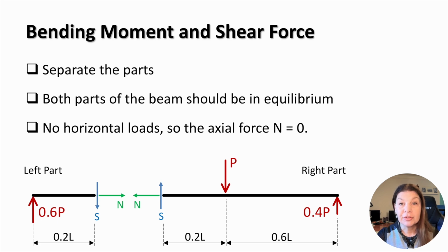As you can see, the force S is added in the opposite directions at the cut in both parts of the beam. This arrangement will cancel the force S if the beam is connected back. And the rotational equilibrium can be achieved through the addition of a bending moment M. The bending moment is also added at both parts of the beam in opposite directions.